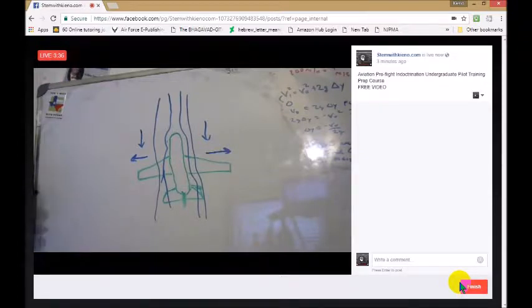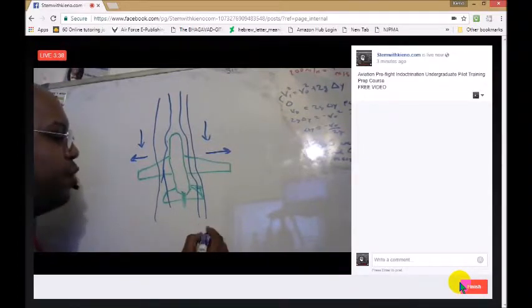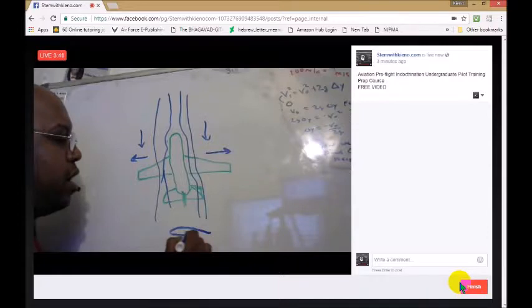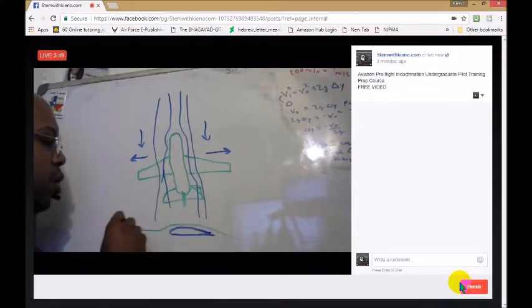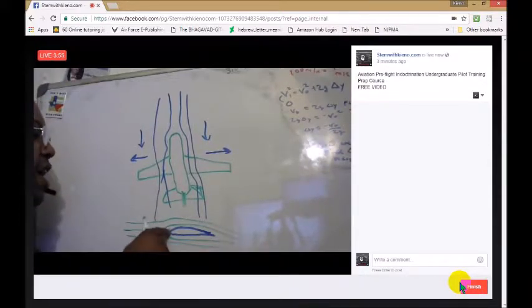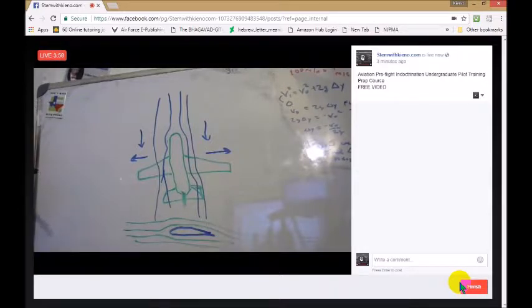If we look at a side view of the wing here, the lift is developed because as we fly through the relative wind, the air molecules have to move faster over the top than the bottom, and we get negative pressure. So back to what we spoke about when we talked about Bernoulli's principle.